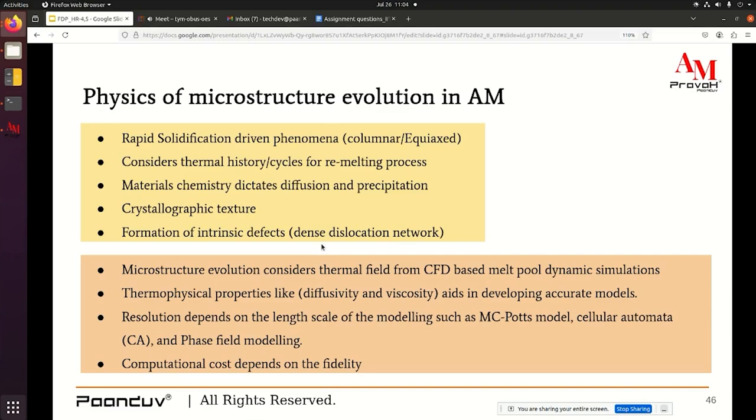Coming to including the thermal conductivity, that will dictate the melt pool geometry, that is the width and depth of penetration, which is generally governed by trivial equations like Rosenthal that will dictate how the geometrical parameters are dependent on the temperature field. To model the microstructure has been a critical aspect since its inception.